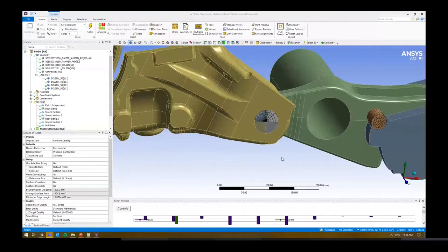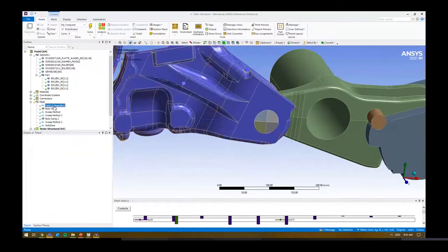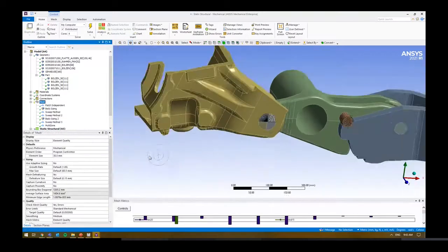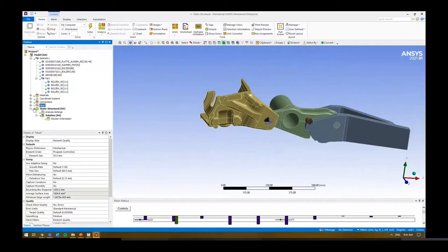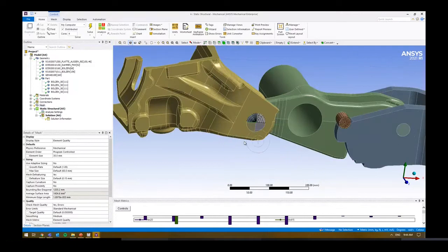All right, so we've got Prasad asking, is the default mesh too coarse? Yes, Prasad, the default mesh is generally a bit too coarse, but is great for a first run analysis. I'll often leave my very first run, get rid of all this stuff, up the adaptive sizing a little bit, and then make sure I've got my boundary conditions all in, right? Make sure I've got it fixed, supported, all my contacts are appropriate, nothing's flying about all over the place. I'll get a solution, and then I'll have a look at the results. Identify if there are any hotspots that I didn't anticipate, and then go back to my mesh and start to make some refinements and some changes around some of those regions as well.